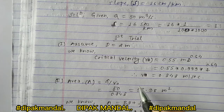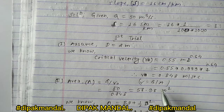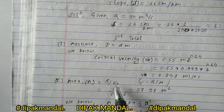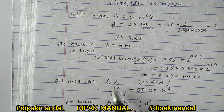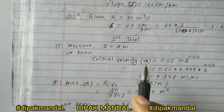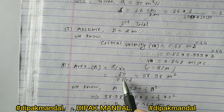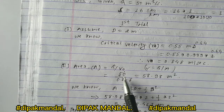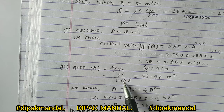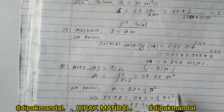As we know, velocity equals Q by A, so we can also write A equal to Q by V. Here the critical velocity is taken, that's why we use V naught. The value of Q is 50, given in the question, and V naught we already calculated as 0.848. So we put these values here and we get the area equal to 58.98 meter square.